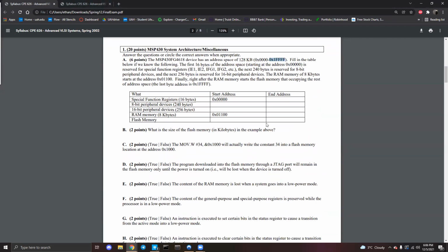And you're done. One thing to note whenever you're filling out these addresses: your start address will more than likely always have a 0 in the rightmost position, and your end address will typically have an F rightmost. Every start address in this block had a 0 at the end, just a quirk of the math. Every time it overflows to the next section, it resets your lowest hex digit to 0. So if you need to sanity check yourself, that's a quick way to do it.